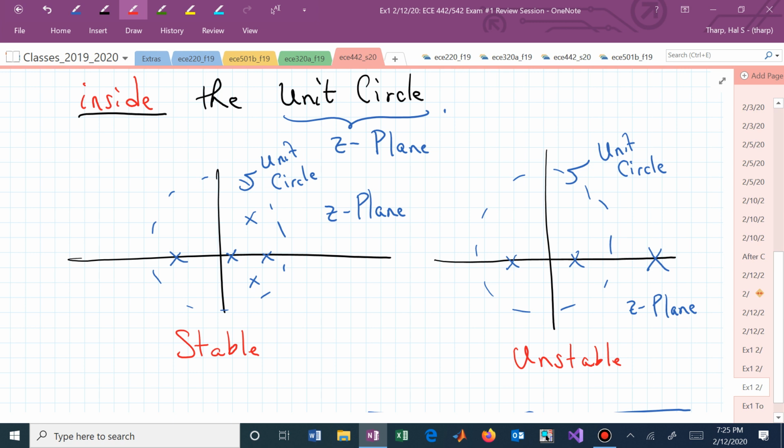I mean, they're related, but they're not. Okay, those are independent concepts. If we have an unbounded region of convergence, that just means the region of convergence, the z-plane, is going off to infinity. That is independent of whether your time domain sequence is bounded or unbounded.